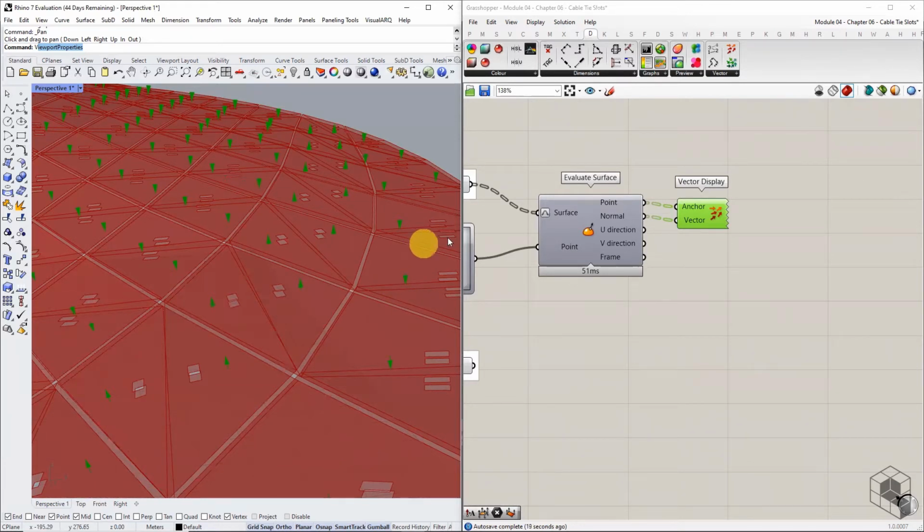To align these triangular faces, we take the warp list, isolate a point on each triangular surface and move it 0.5 mm along the normal vector, and negative 0.5 mm along the normal vector. Then check the proximity of this translated point from the triangle surface on the weft list. To check for similar orientation, the distance of the 0.5 mm translated point should be greater than the negative 0.5 mm translated point. Isolate a point on the surface using Evaluate Surface.